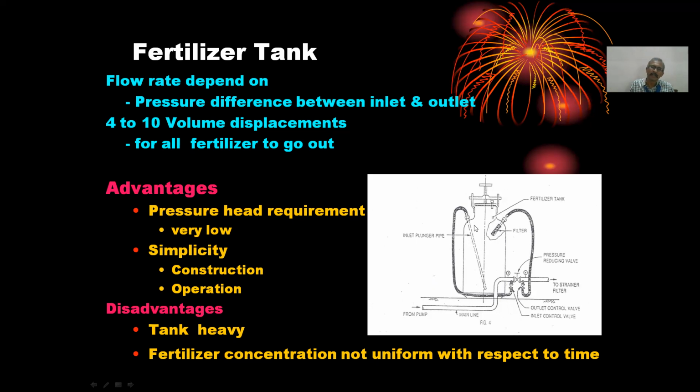And normally they are designed in such a way that if 4 to 10 times volume of the fertilizer tank water is passed through this tank, all fertilizers would get into your system. So that should be kept in mind.